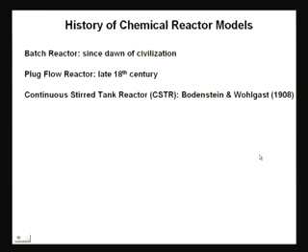It turns out this is a big conceptual leap as far as the whole idea of chemical reactions and chemical reactors was concerned, okay, because as I said, it's portable, it takes less space, and at the same time it has continuous inflow and outflow, and that kind of revolutionized the whole chemical industry. And if you now look at chemical industries, almost all chemical reactors are CSTRs, or continuous stirred tank reactors. Only a small percentage of them would be batch reactors.